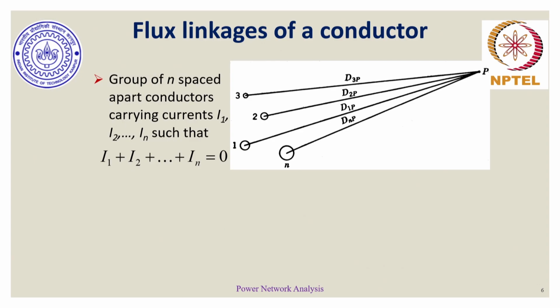Moving on to a set of conductors, we are complicating the situation more and more. Earlier we focused on only 2 strands or 2 conductors. Now we are focusing on n number of strands or n number of conductors, because actual ACSR conductors are made up of different strands, and the number need not be only 1, they can be more than 1. In this set of strands or conductors, we assume that at least one of those conductors is acting as a return conductor for the entire circuit.